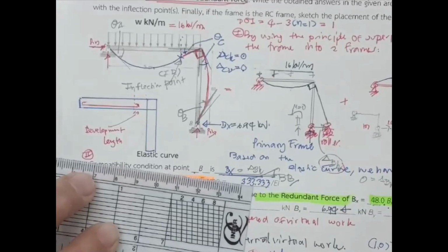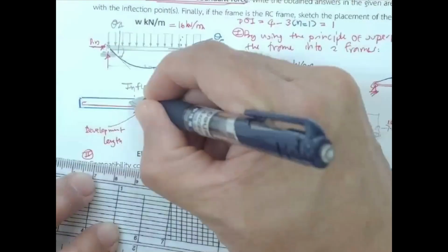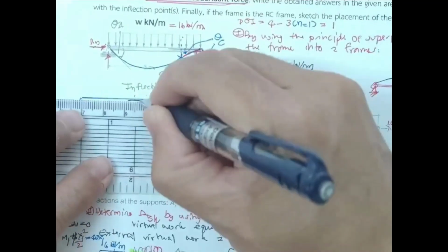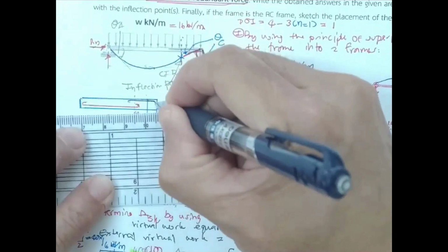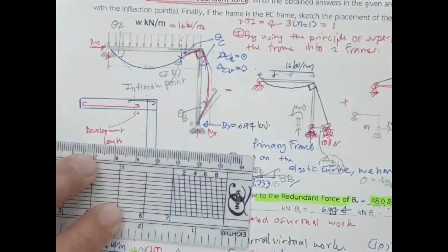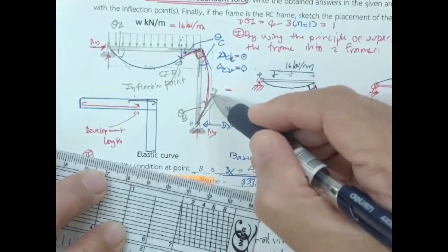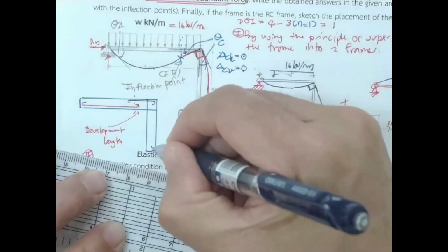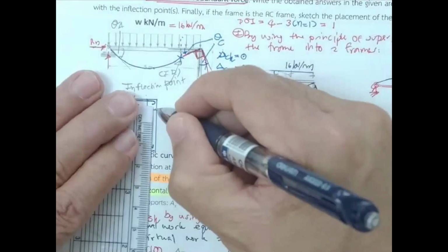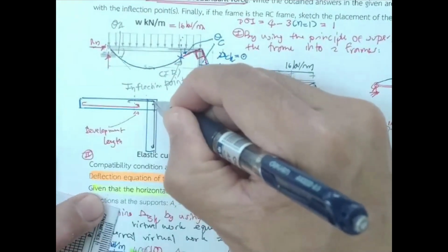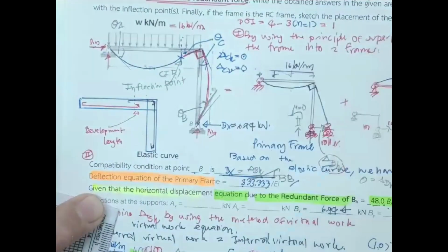And also for this top portion, you may put this one. This is negative moment, and then you have this one for taking the negative. And for this one, you have the tension on this surface. So just put the reinforcement something like this. Sometimes you may connect it together, make it one piece.